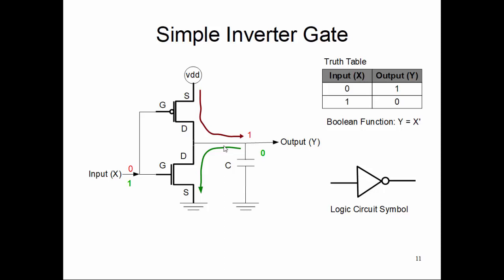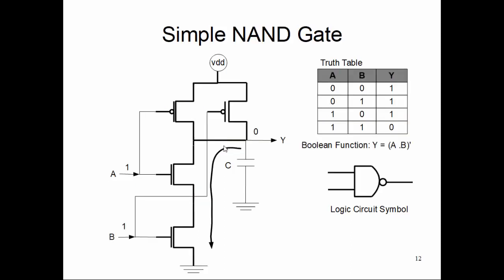With this same understanding, let's try to understand the NAND gate. Okay, NAND gate configuration is somewhat like this: two NMOS stacked on top of each other. One is driven by, let's say, logic input B, another is driven by logic input A. And then the PMOS are in parallel with each other but stacked with this NMOS stack.